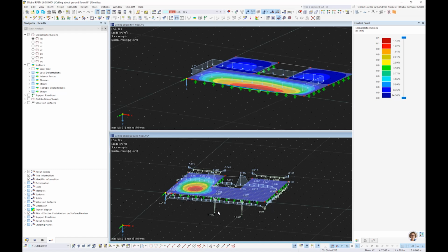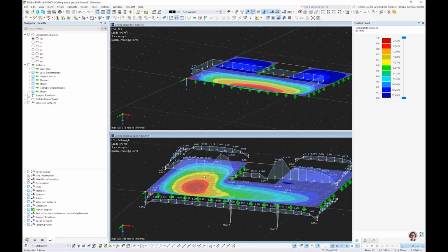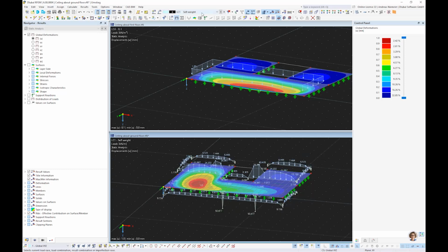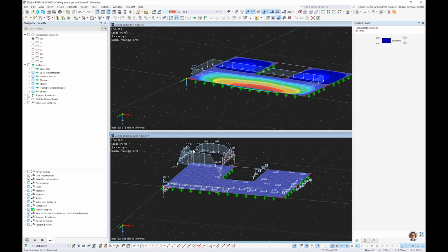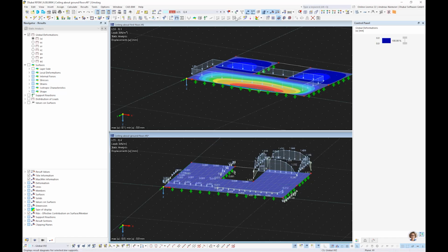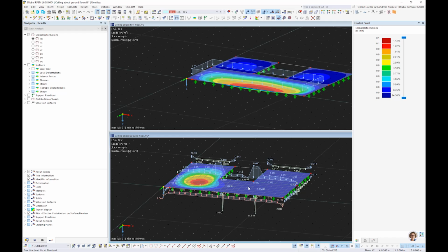And what is really nice now, you see the surface weight is clear, it's a permanent weight, and also in the case where we have a wall on top but not below, you also get a load here as free load. The regular load cases are not used as defined in the table, and here we have the loads from the separate load case, from this room and from this room. And this is a really efficient usage.